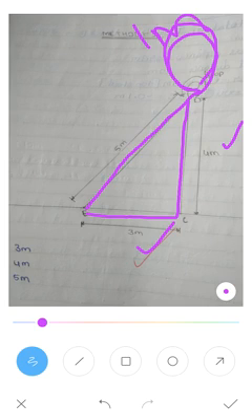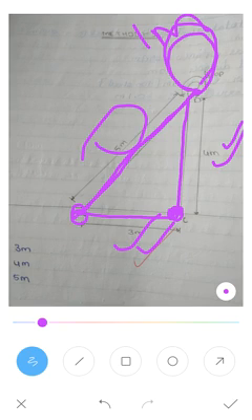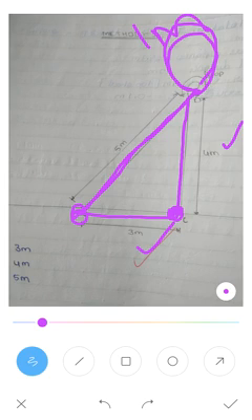Then take another point. You stick one point here and another point here. At a peg you fix it, make a loop of 1 meter and run 5 meters to here and join. So this is 3 meters, this is 4 meters and this is 5 meters. The hypotenuse will be the highest length. This is the 3-4-5 method, which I explained in the simplest way.